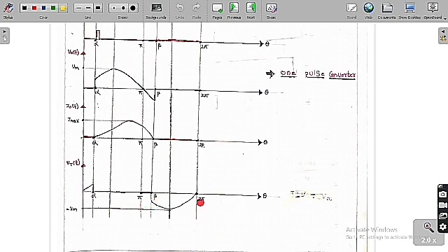From beta to 2 pi, it becomes like an open circuit, and again the thyristor voltage is equal to the source voltage, blindly following it. So the peak inverse voltage is equal to Vm. And from beta to 2 pi only, the thyristor faces a negative or reverse voltage. So the circuit turn off time is equal to (2 pi minus beta) by omega.